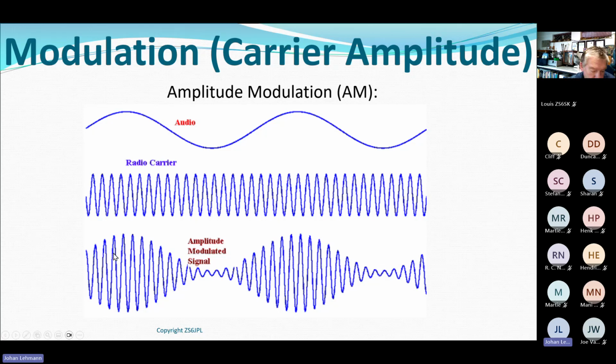It's a difficult one, and we'll get to it now. If I overmodulate, in other words, I change the amplitude of my carrier frequency too much, I create distortion and I create harmonics. So if you get the question in the exam paper, when does distortion occur in an amplitude modulated signal? It's when I overmodulate, so I modulate more than 100%.